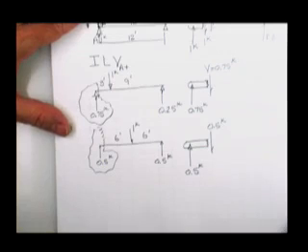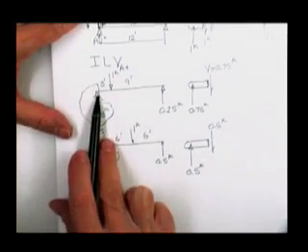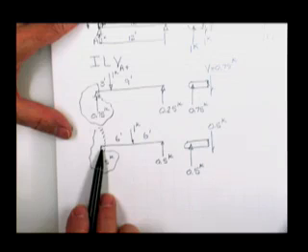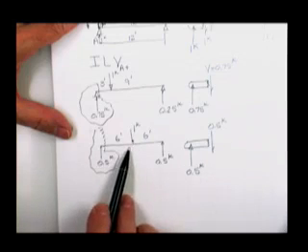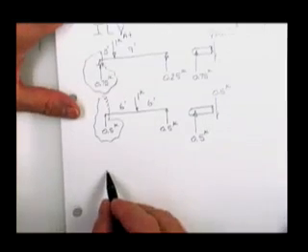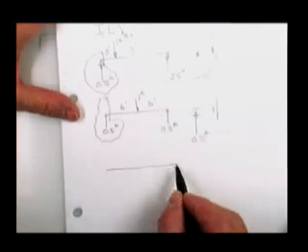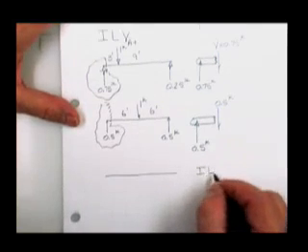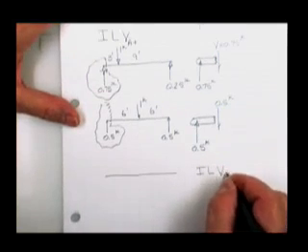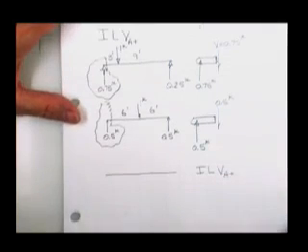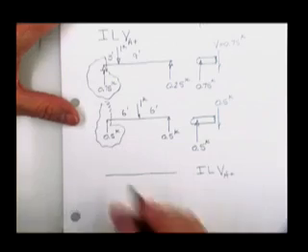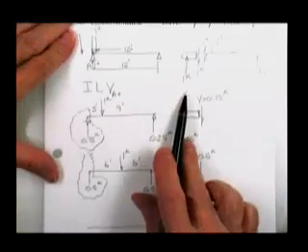You plot the answer for the shear at this point where you put the load. That's its influence. And therefore, here is the influence line for the shear at A+, slightly to the right of A. The first value is 1.